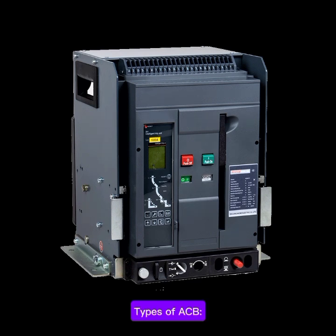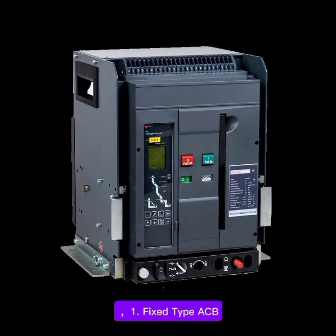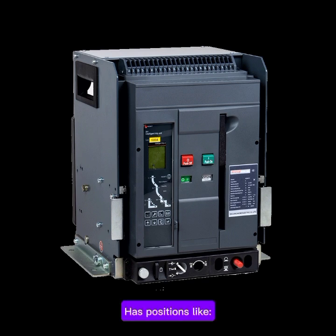Types of ACB. There are different types of ACB based on construction and operation. 1. Fixed type ACB, installed permanently in panel, cannot be removed. 2. Draw-out type ACB can be removed from panel easily. Used in industries for maintenance purpose. Has positions like connected, test, disconnected. This type is more popular.